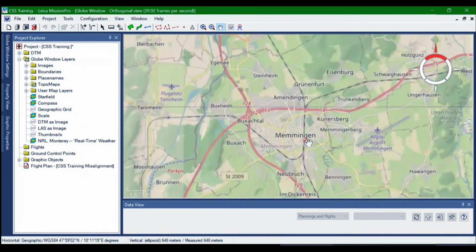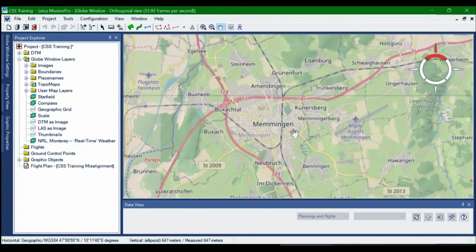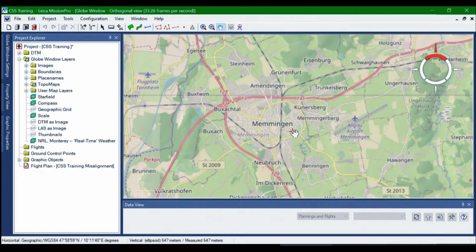How long does the run need to be, ideally, Paco? Sorry? How long does the run need to be, ideally? How long? Yeah. Oh, I would say half an hour. No, but like line length. How long the line? As far as I remember, for oblique camera, it should be at least 10 kilometers.